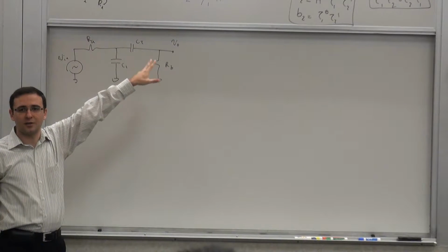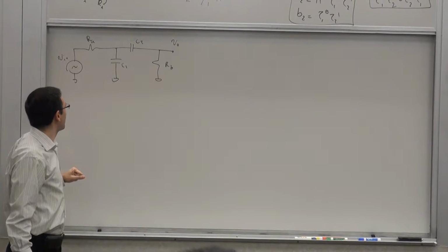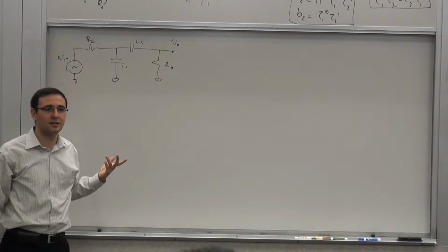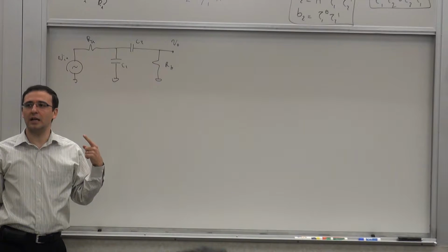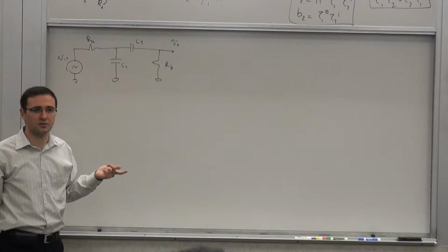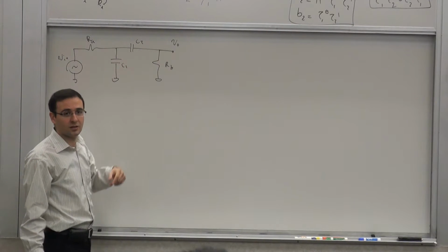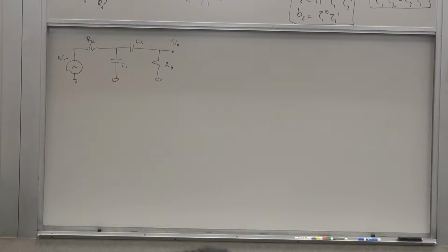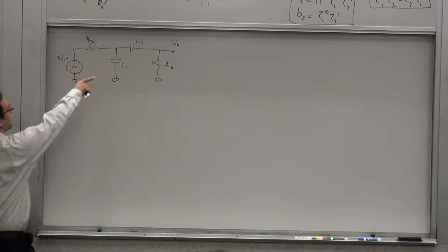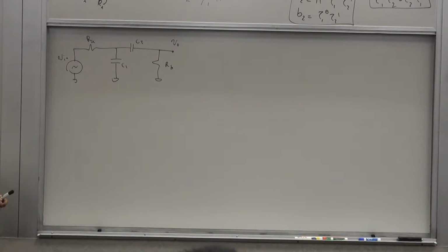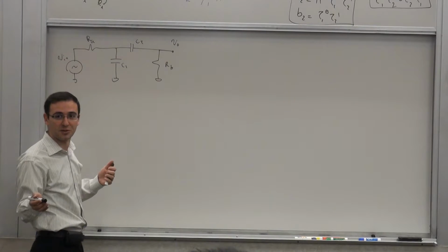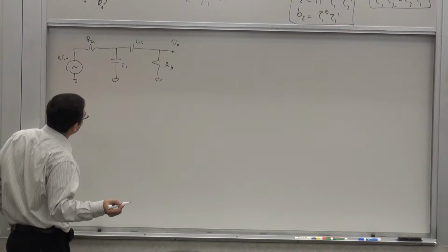Independently. I don't have a loop that will limit me in that case. How many zeros? There's one element, infinite valuing of which results in a non-zero transfer function. This one. So 1 zero. Left half or right half plane? Left half plane. Why? It doesn't change the polarity, exactly. So make sure this doesn't change. So I'm expecting 2 left half plane poles, 1 left half plane zero. And if I get anything else, then I've done something wrong.